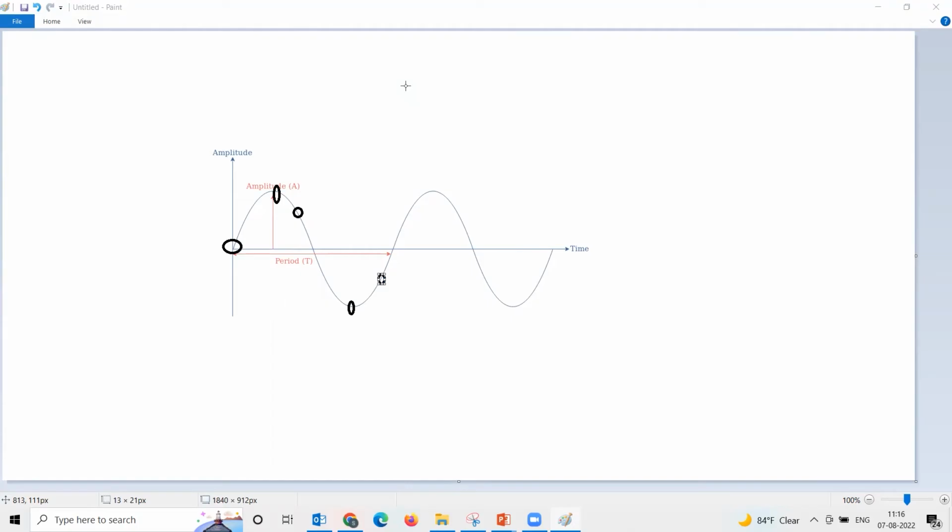So you have to probably think about both extremes, but predominantly we are performing short circuit studies to understand or select the right switchgear rating. Hence, the maximum case is enough, and ETAP does that, and we are happy. And if somebody says the ETAP result and the real-time fault current, the simulation, are not matching, it will never ever match.